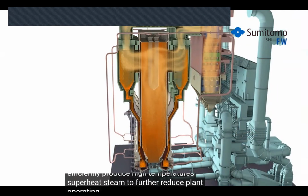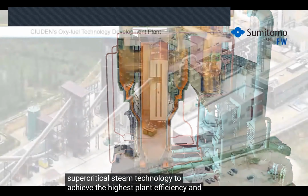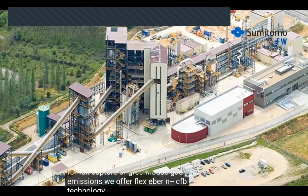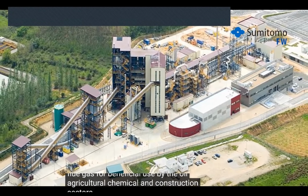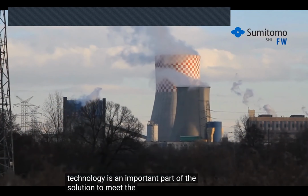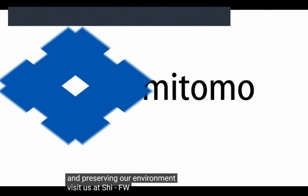To further reduce plant operating costs and emissions, our CFBs can utilize vertical tube supercritical steam technology to achieve the highest plant efficiency. And for full capture of greenhouse gas emissions, we offer FlexiBurn CFB technology which can produce a CO2-rich flue gas for beneficial use by the oil, agricultural, chemical, and construction sectors. Circulating fluidized bed technology is an important part of the solution to meet the world's energy needs while conserving natural resources and preserving our environment. Visit us at shi-fw.com for more information.